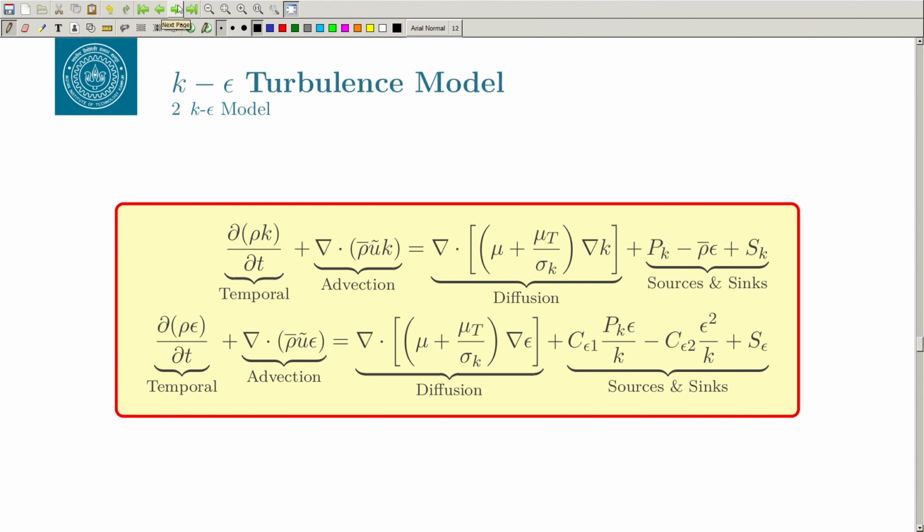Okay. Yeah, so this is again I have put all the equations together, okay, for the k and for the epsilon, and I have basically indicated different terms. Okay. So, this is the production of kinetic energy and dissipation, and based on the model we have the production of the dissipation rate, if I can call that, and this is the dissipation. Okay. So, these are all model terms.